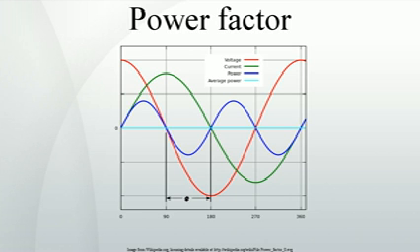A typical multimeter will give incorrect results when attempting to measure the AC current drawn by a non-sinusoidal load. The instrument senses the average value of a rectified waveform. The average response is then calibrated to the effective, RMS value. An RMS sensing multimeter must be used to measure the actual RMS currents and voltages, and therefore apparent power. To measure the real power or reactive power, a wattmeter designed to work properly with non-sinusoidal currents must be used.